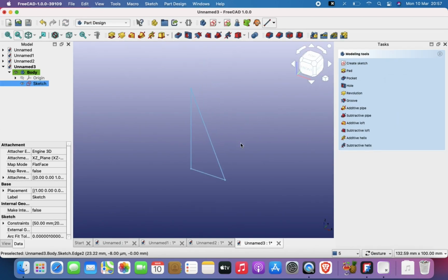You may be expecting me to do an extrude or a cut. In fact, I can't do a cut here because I don't have any solid feature yet. But in this video, I want to do a revolved operation. What does a revolved operation do? A revolved operation simply spins a sketch around a given line or a given axis.